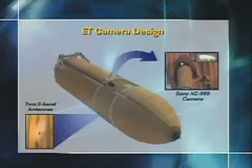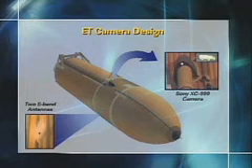The next graphic shows the configuration of the ET camera. On the bottom left-hand side, these are the S-band antennas, again the same as used on 112, except this time we've moved both of the antennas to the back side of the tank to keep them from being any debris source to the orbiter itself. The camera, shown on the right-hand side, is up in the feedline fairing housing looking back down the tank, and as I mentioned, the camera is in this new casing that's in the little inset so that it would fit up there in that feedline fairing housing.